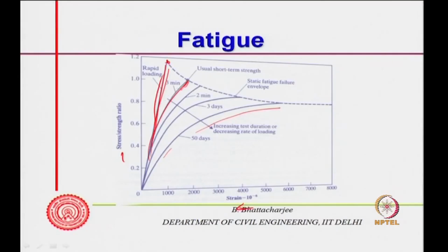So, if you go on increasing, this is the normal stress strain diagram, but if it is 3 days, if you keep the load for 3 days, then at 80% of the static load it will fail.